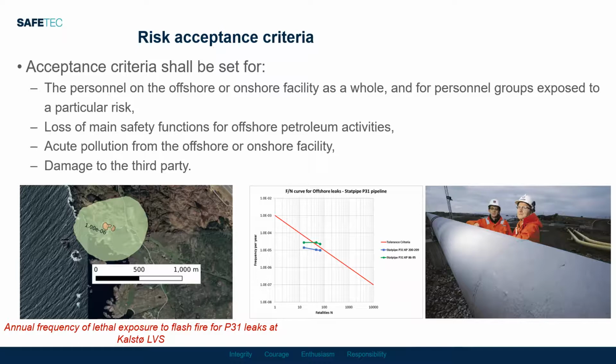Dr. Amarnath, I think we are heading in the right direction. I think your presentation has set us off on the right direction. Just a technical point. Since we are talking about risk acceptance criteria for refineries as well as for offshore facilities, I would just like to know whether individual risk contours are applicable for onshore facilities, or should we go for societal risk factors such as FN curves? Because I don't think IR alone is going to be sufficient for something like a refinery.